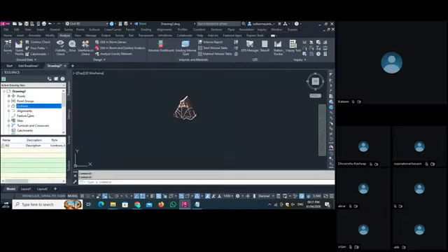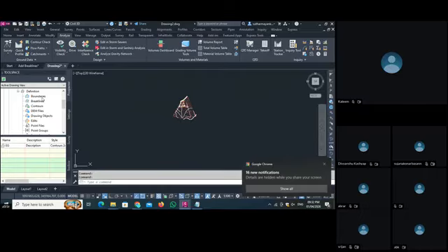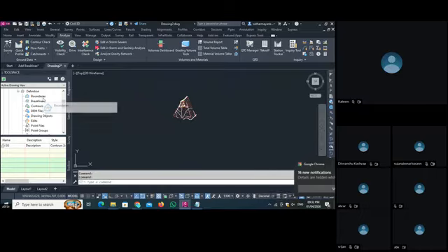So what we did now, under the surface, we created one surface named easy. Now you see a plus icon here in the easy surface, and here you can see mask, water shades, and definition. Now we are working with the definition parts. When you click this plus icon, you can see boundaries. If you want to set the boundaries, you can set them with the help of this boundary.